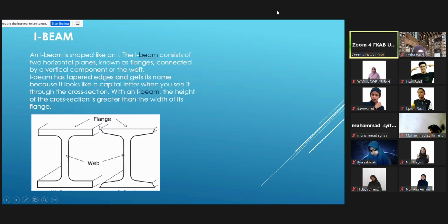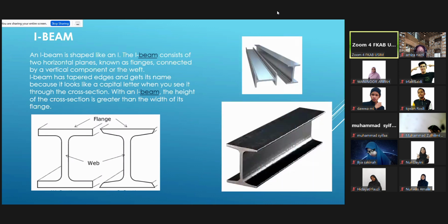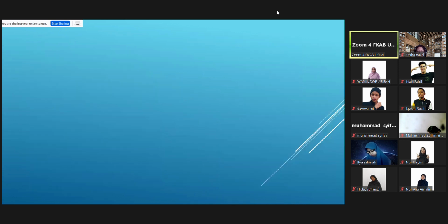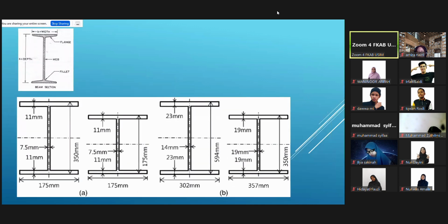If you're talking about column, normally it's called the H-beam. For the I-beam, the web is longer, because for H, basically equal dimension, they use it for column. This is the raw material of the I-beam. Its load is more, if you go by horizontal, what they call beam, I think 3 or 4 times more than the normal cross